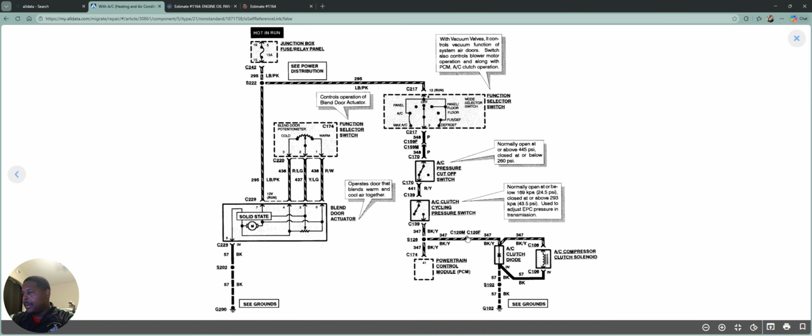So I am testing the black and yellow wire on this side and here, switch unplugged, compressor unplugged. Switch your multimeter to ohms resistance and test the resistance of this wire, because you want to see if there's a bad splice, if this connector is messed up, corroded, not plugged in all the way, or whatever have you, or there's a break in the wire.